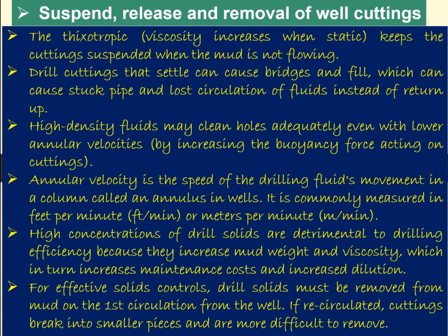The next, I will further discuss on specific conditions. You will understand. High density fluids may clean holes adequately even with lower annular velocities. Annular velocity is what? Annular velocity means the fluid injection velocity, with the cleaning aided by increasing the buoyancy force acting on the cuttings.